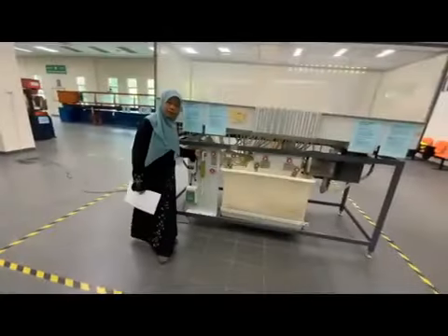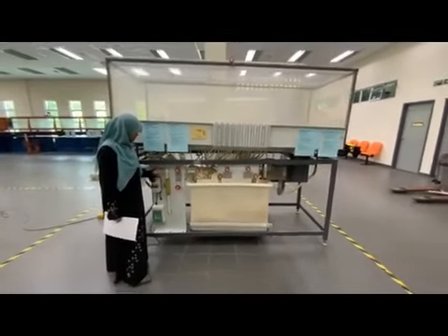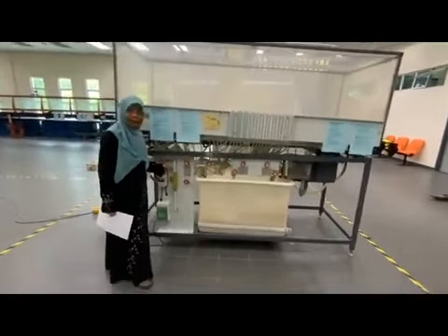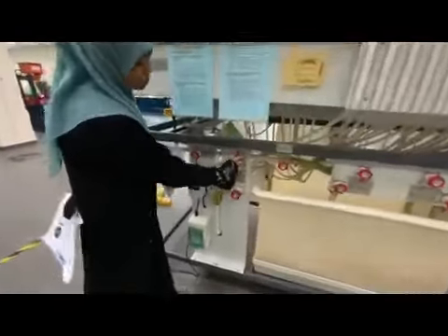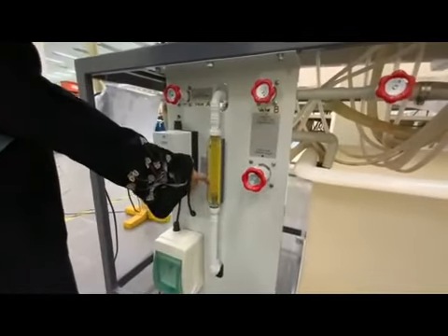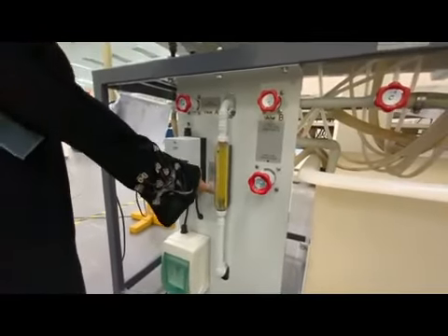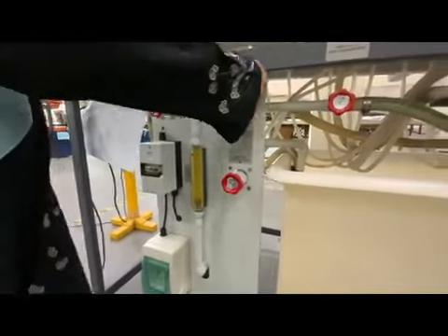First, on Table 1, you need to have the data of the relationship between the depth and the discharge. This is the valve. What you need to do is turn on the valve, and you will see the rising of the water level, determining the discharge of the flow going into this part. It will outflow into this container.